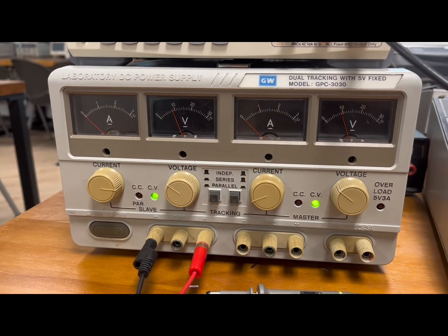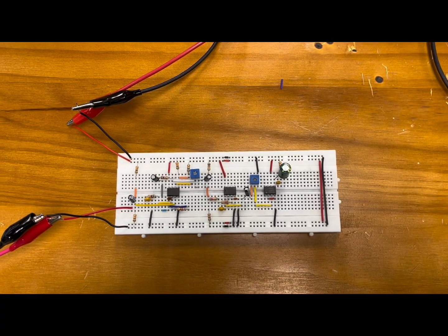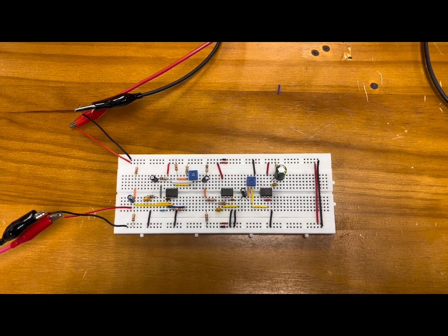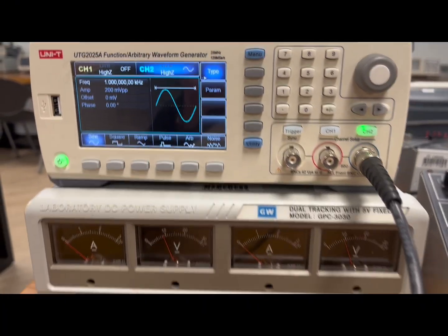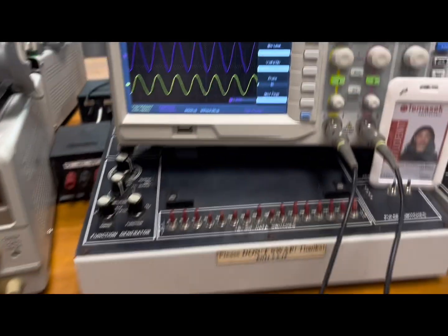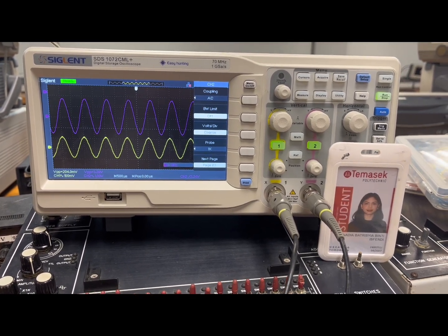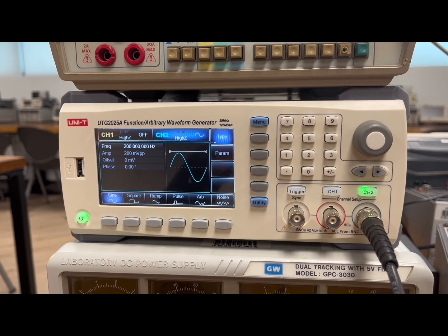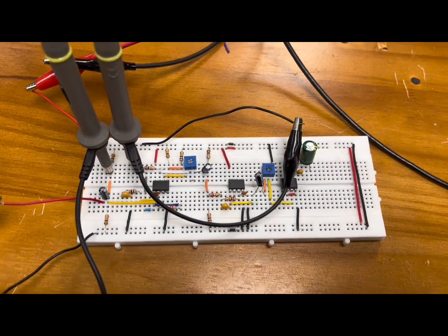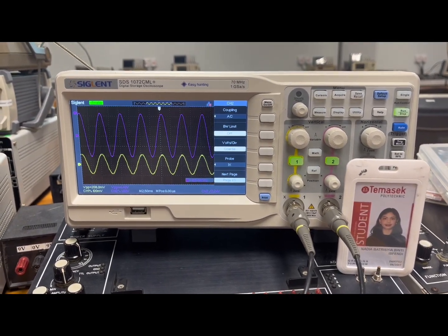To set up stage 1, firstly, the power supply DC source is set to 9 volts and is connected to the circuit. Secondly, connect the function generator to the input of the circuit. At 1k Hz, using the oscilloscope, we will place channel 1's probe at TP1 while channel 2's probe at TP2. The output voltage is around 3.28 volts peak to peak. Set the frequency to 200 Hz without altering any other parameters. The output voltage is 4.4 volts, which is more compared to the previous voltage.